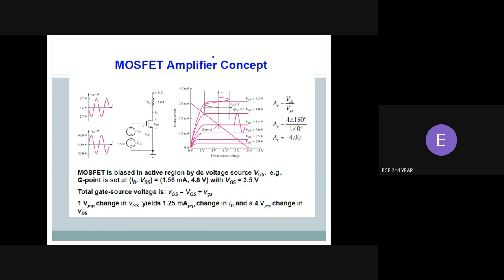In other words, we can control how the MOSFET operates by creating an enhancing connectivity channel between the source and drain regions, providing a type of MOSFET commonly called an N-channel enhancement mode MOSFET, which simply means that unless we bias the gate positively, or negatively for P-channel, no channel current will flow.